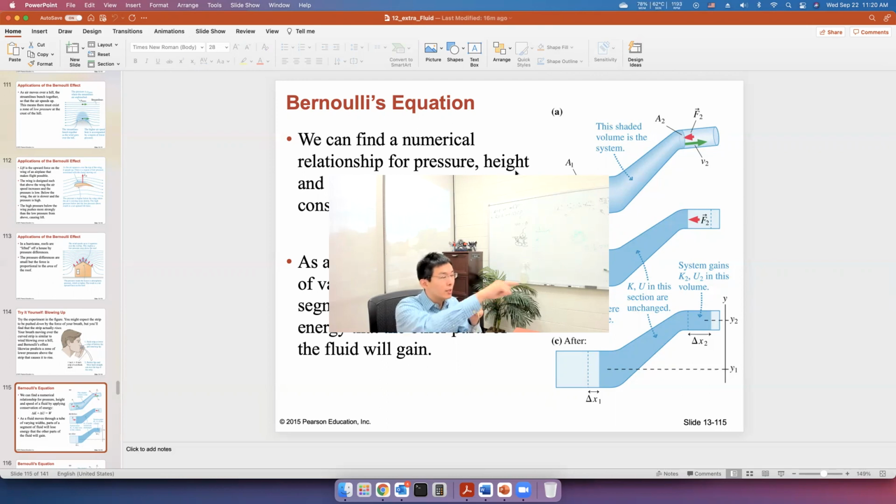So when this area has a lower pressure, there will be a pressure difference. The pressure below this area is high and in this area is low. So the pressure will push the strip up, so that you can see the strip is going up. So that's the experiment of the Bernoulli effect. You can do it by yourself.